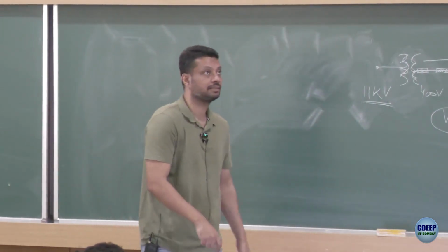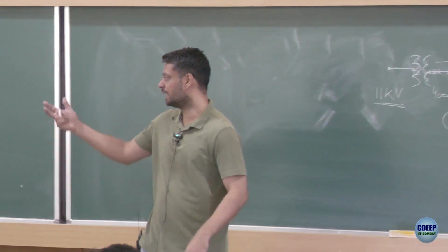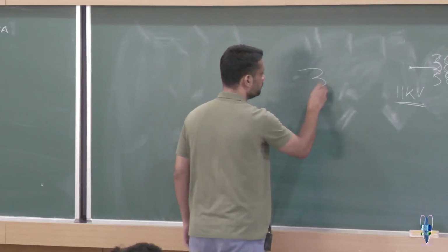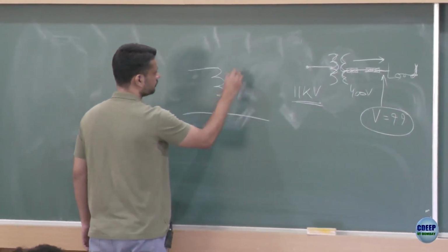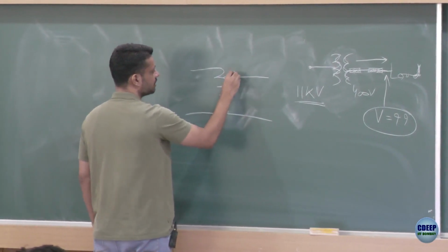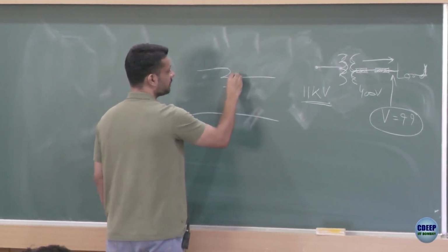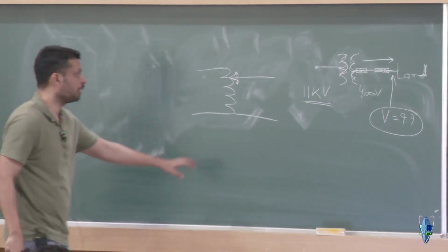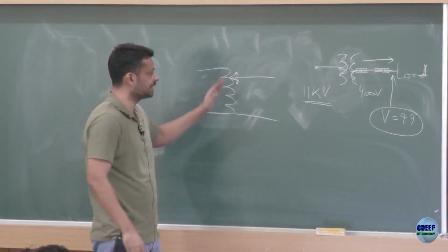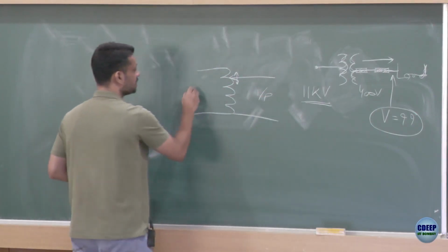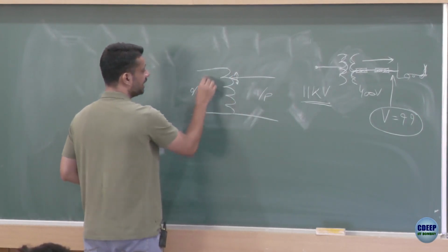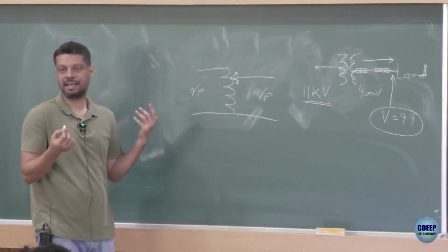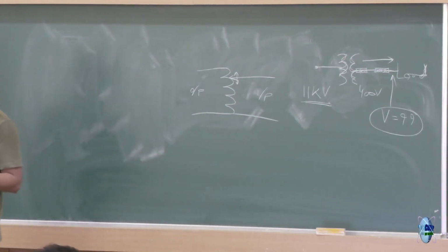So what you can do is, in this room for example, I can connect an auto transformer. As soon as power comes in there, it will go to an auto transformer. And then I can change the number of taps in the auto transformer by rotating that knob, right? That would adjust my output voltage as compared to the input voltage. So I can get a higher output voltage as compared to the input voltage, right? So the basic principle is, yes, you have to use some form of auto transformer.